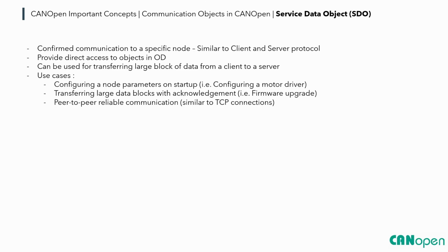So SDOs. If I want to compare to networking, it's a very bad example, but I think it helps you understand. PDOs are like UDP packets, so you just transfer them. Although in UDP packets you may specify the destination address, in PDO we usually don't do that, so we just broadcast. We broadcast a UDP packet, and whoever is interested in that packet will copy that information.